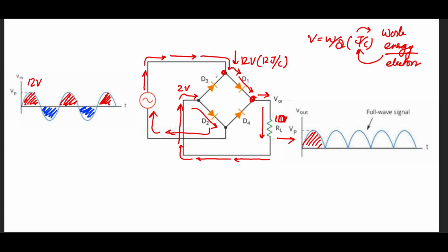The negative current actually starts from this point, from this direction. It starts reverse to the direction of the positive current, which was red. It moves in this direction, comes to this point, and then it has 2 paths to go. It can go towards this side or towards this side. And we know by this time it will reject this path because the arrows do not match. So it chooses this path, D4, to go through.